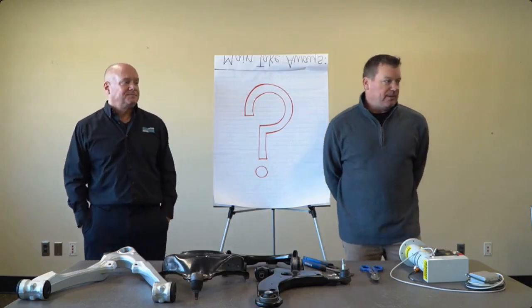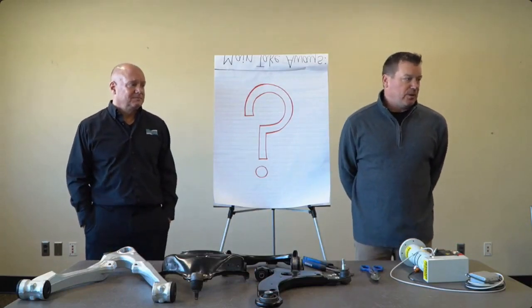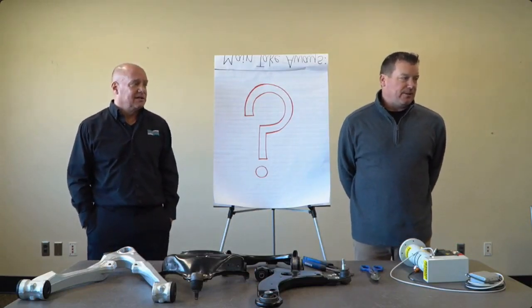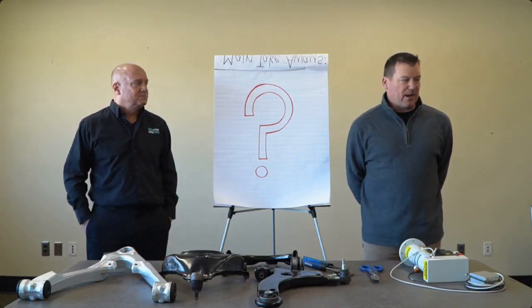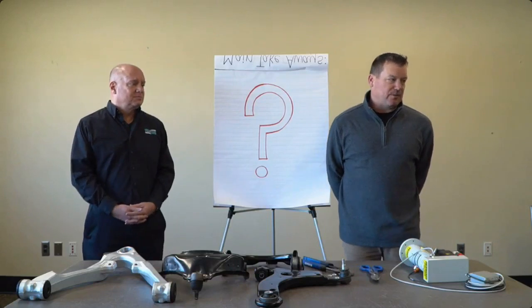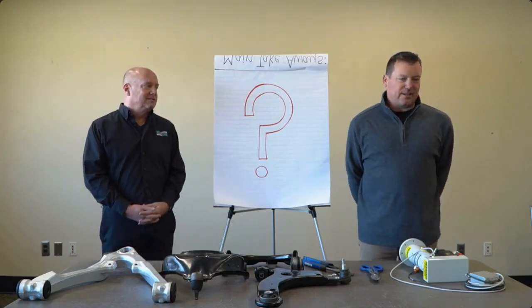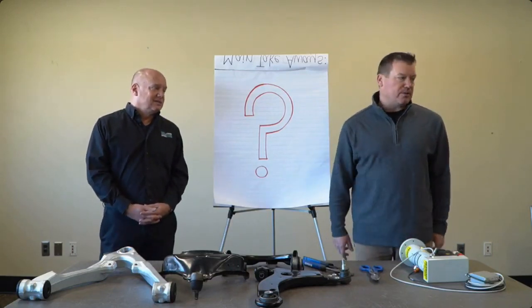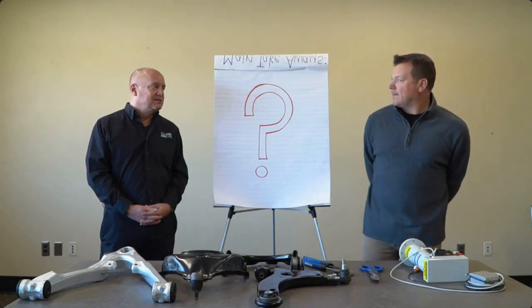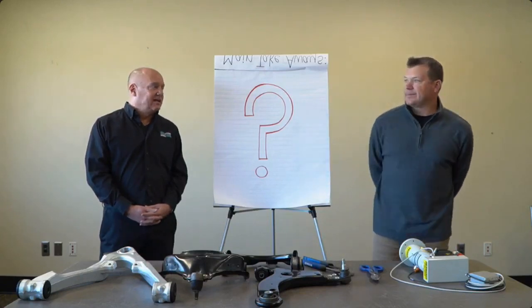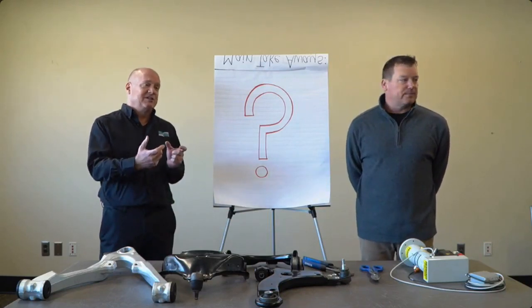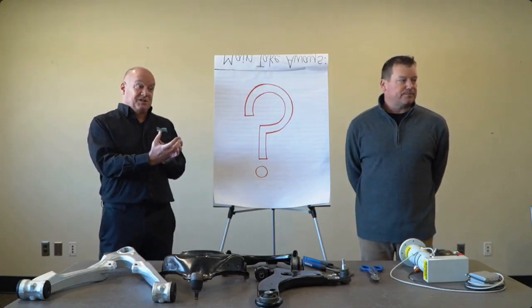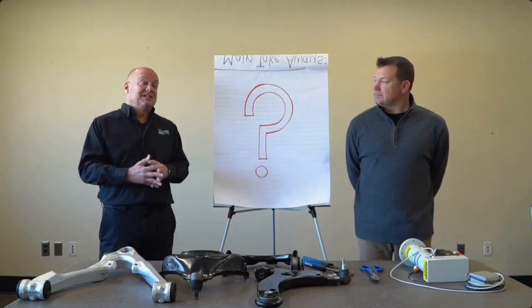How many LVDTs can you use? So it's really unlimited. With our Ultra Pro system, it's very modular, so we just add modules that can take in more analog and encoder inputs. The Ultra Pro system is EtherCAT based. So you just keep adding in what we call digital signal conditioners.